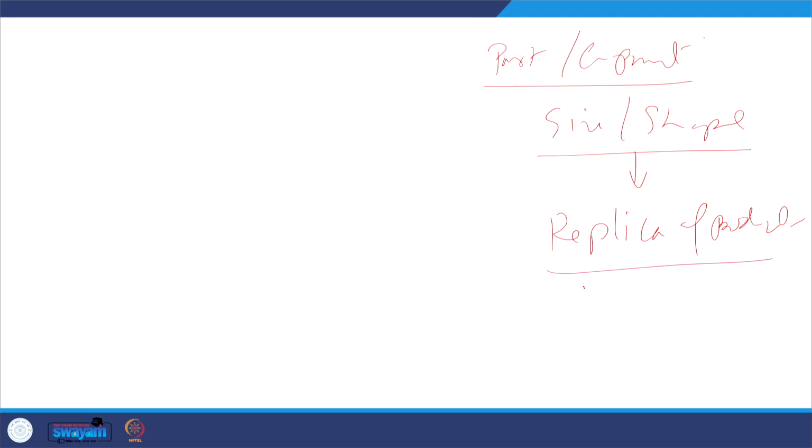This replica is known as a pattern. This pattern can be made of wood, metal or plastics, depending upon the size of the component, the number of units to be produced, and the dimensional accuracy desired. So, making the pattern is the first step.